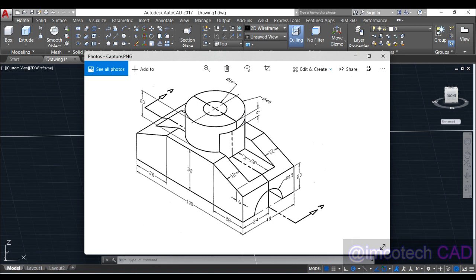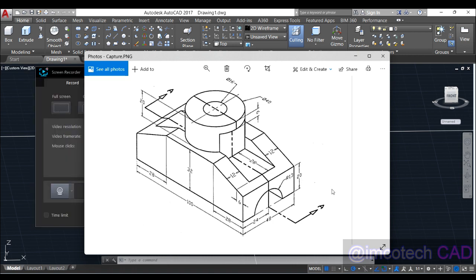Therefore, for this cut here, we are going to make a cut up to a particular position, and I don't know the height. The height was not given. Therefore, I will use this 6 as reference point. I'm going to make a line here, or I'll simply offset this construction line by 14 units up to make this position. You could do this in 2 ways. You could make a line up here and take it down by 6, that's offset by 6 units down, or use this construction line around this center, around this 20 downward, and then offset it by 14 up.